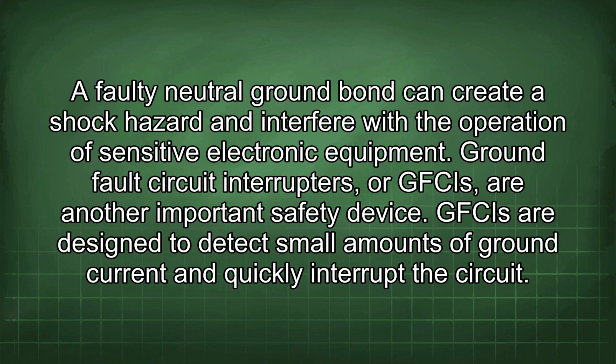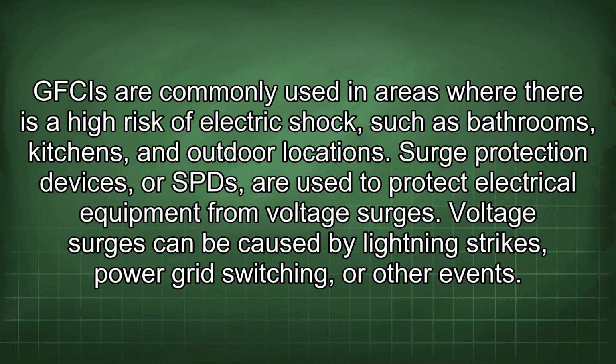Ground fault circuit interrupters, or GFCIs, are another important safety device. GFCIs are designed to detect small amounts of ground current and quickly interrupt the circuit. GFCIs are commonly used in areas where there is a high risk of electric shock, such as bathrooms, kitchens, and outdoor locations.